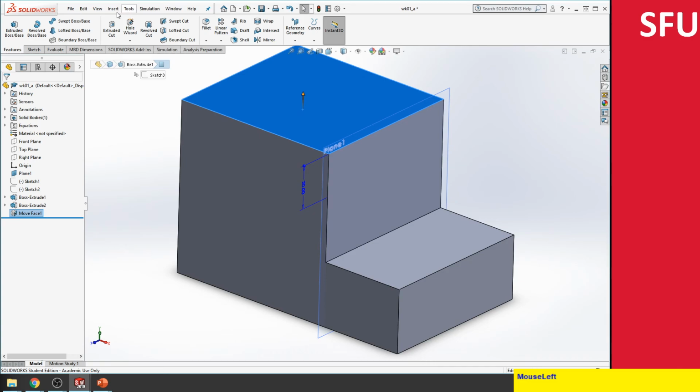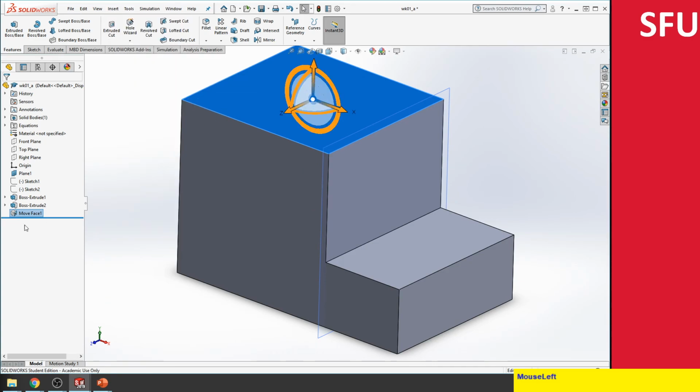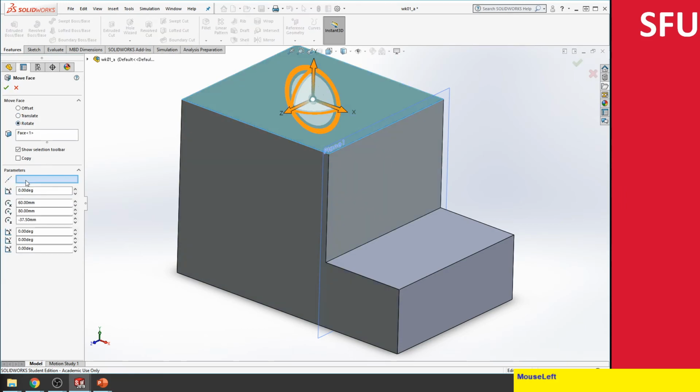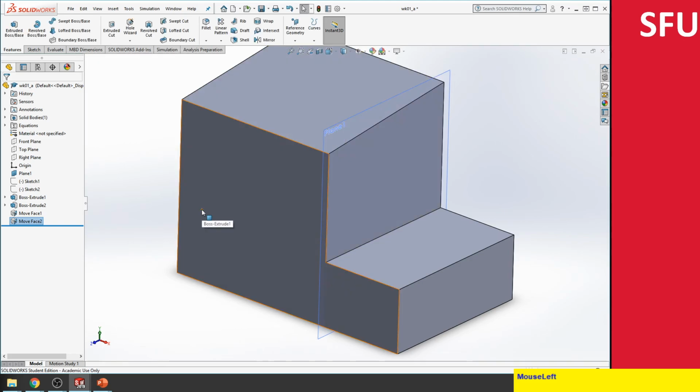So maybe select this new face again, insert face. Let's see if we can do something else. Move. Maybe let's see if we can actually rotate this. So here I need an axis. Obviously it makes sense to rotate about this axis over here, and then select this, and maybe give it a couple of degrees and see what actually happens. So maybe we flip directions, and now it's going up, and then we say okay, and now we have directly moved all of those faces.